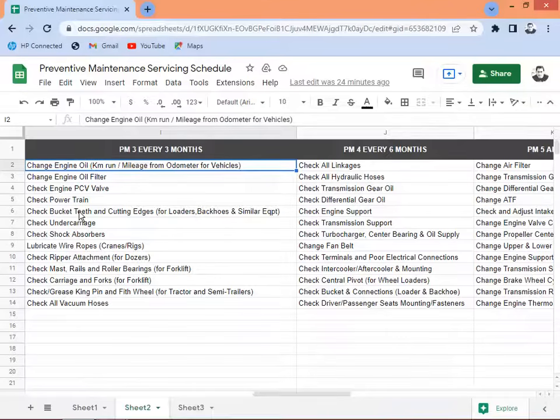Okay, you have to check the sulfur content of the used oil. Whether the sulfur content is higher, then you make adjustments. You make it shorter, the kilometer run.